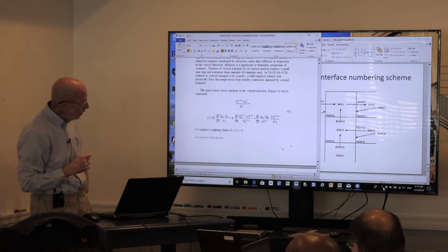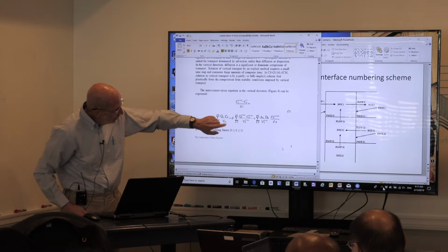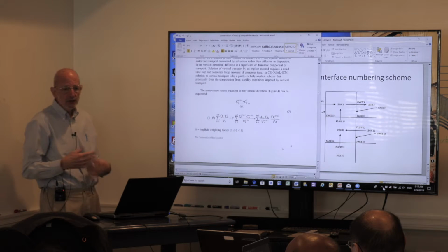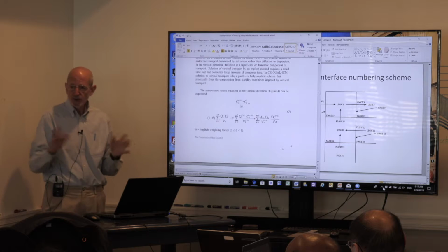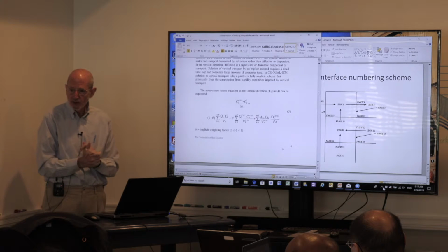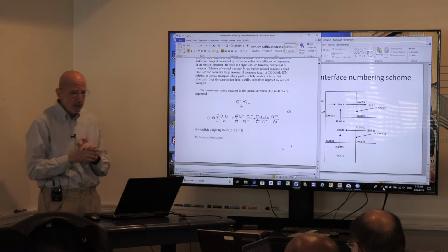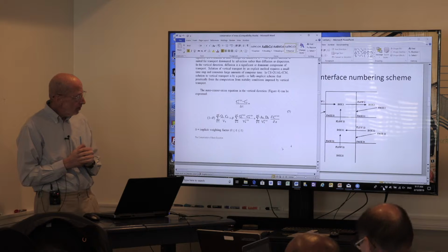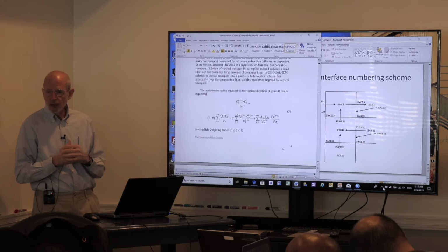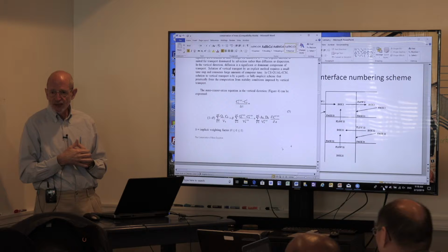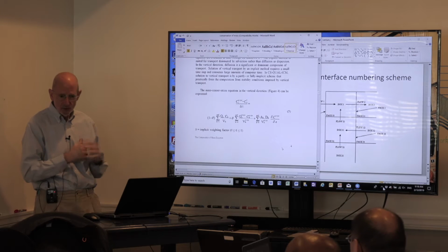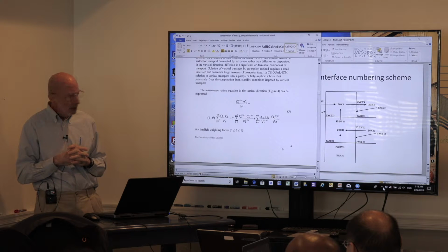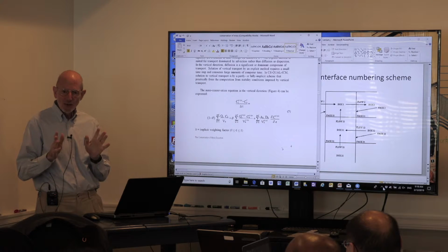If theta equals 1, we're going to work exclusively with the future time. And that's a fully implicit numerical scheme. I'm dropping buzzwords, but for those of you who are familiar with that sort of thing, that's a fully implicit scheme. We like fully implicit schemes because they have good stability properties. On the other hand, we don't like them because they have a lot of numerical diffusion associated with them. They have some undesirable properties. So they're stable, but they have undesirable properties.